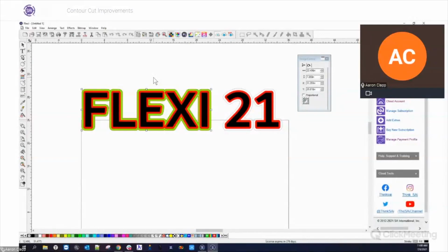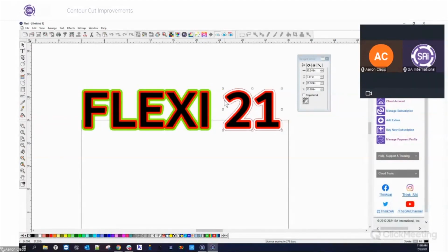And then, of course, now we've added the ability for you to assign a contour cut color in Production Manager so it can recognize that color, since it doesn't have a design interface to do that. So that's why that's there. But it should only cut once, unless you've overlapped it or duplicated the line more than once. But in this case, when I converted this to contour cut color, it converts it from one element to another is what it does.